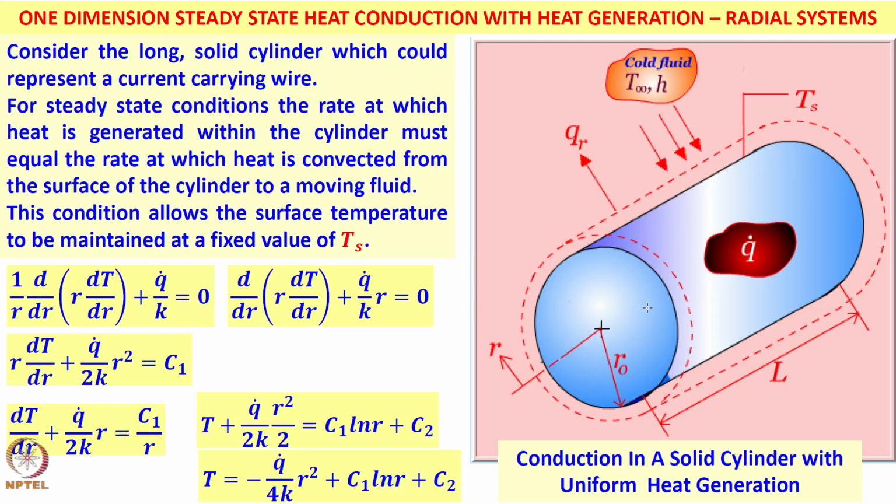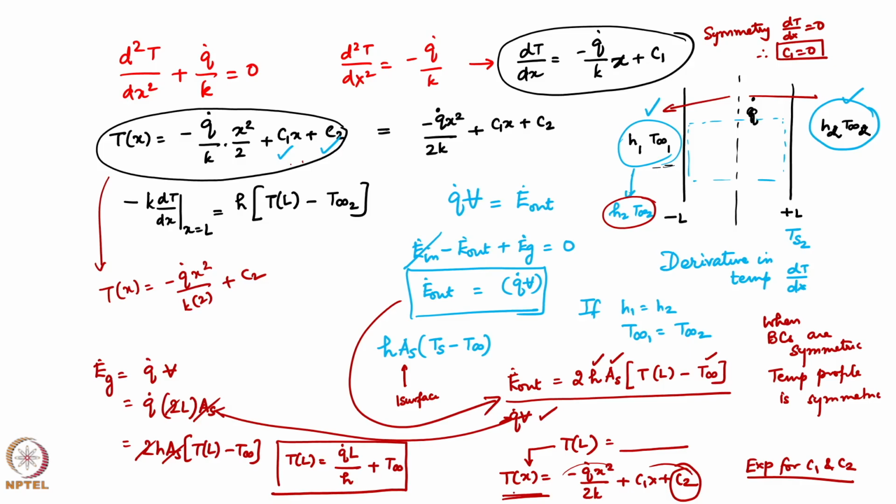Okay. So, again here uniform volumetric heat generation will give me the center line to have the maximum temperature. So, this is a very useful common geometry right from current carrying conductor to a nuclear fuel rod. The fuel rod is generating heat, and the heat transfer is basically 1D radial conduction in a cylinder. Just as a plane wall, this is now a cylindrical geometry.